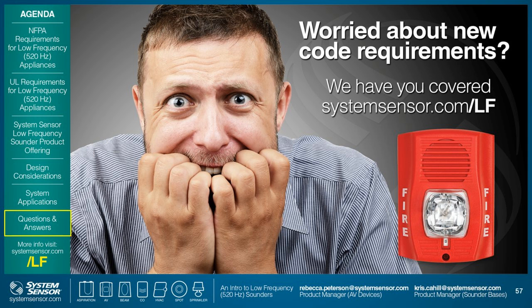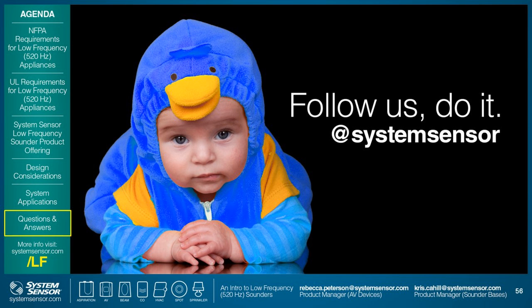Okay, all right. What about proof of low frequency compliance? So how do we provide proof of low frequency compliance of a voice system? I think I mentioned this earlier. You're going to have to check with that amplifier manufacturer to provide you with the compatibility document that was approved by UL, or they're going to have to provide you with some sort of letter or justification from UL. Because UL does not publish compatibility on the online listing directory.